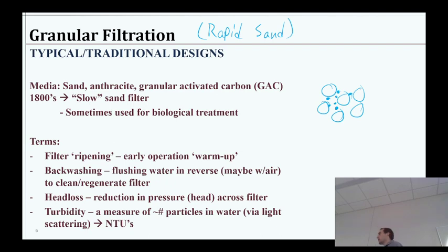Finally, turbidity. I think we probably mentioned it before. Turbidity, I'll explain here. It's a measure of how many particles there are in solution. We look at this just by seeing how much light is scattered away based on those particles. So we talked about it, I think, in sedimentation. And so we can monitor turbidity after the filter to make sure that we are not having a scenario where particles are escaping. Because if turbidity is increasing, that means particles are escaping. That's not a good thing.